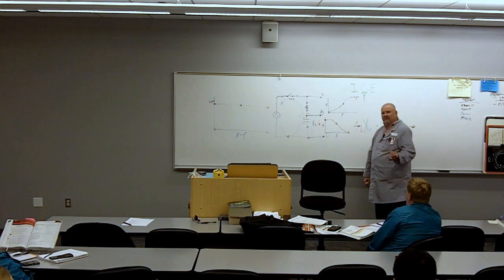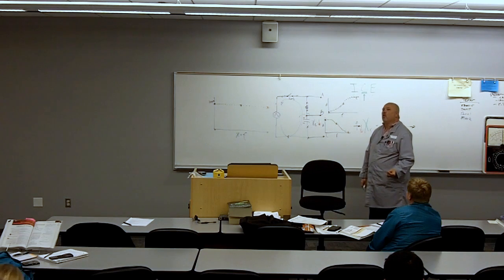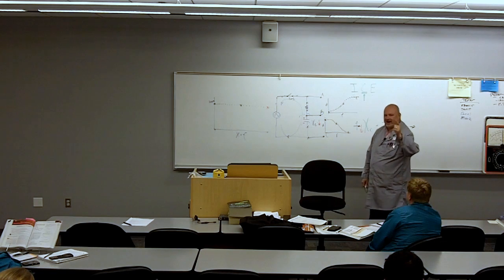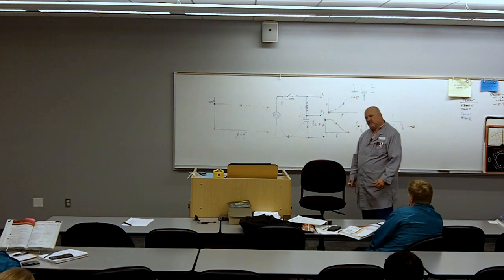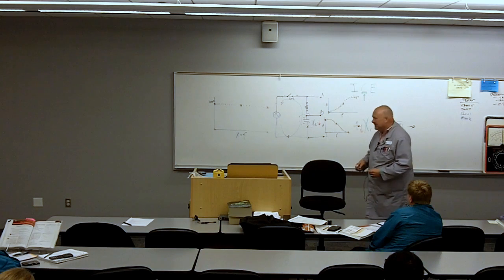And the difference between a low pass filter and a high pass filter is what? Where I connect my output. It's that simple. Both low pass filter and high pass filter are both examples of series, AC series, RC circuits.